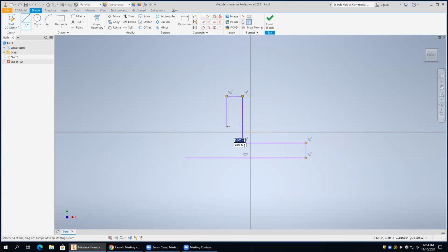We want to be a little bit above it. And we're going to come over. We're going to come up until, notice that little line that pops out. That's telling me I'm coincident with the top of that. So I'm going to be there. Then I'm going to come over until I get another line that dashes out. Then I'm going to be there, and I'm going to bring it down. So there's my figure. And these little symbols that you're seeing here, these are called constraints, and we're going to talk about these next. So what that's saying is that's a perpendicular constraint, okay, which is important. You can add those or remove those later on, but we're going to just keep those as they are right now.